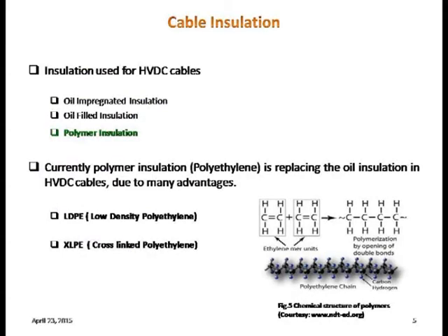So if the two power systems are connected through cable transmission, which is DC, then there will be more scope for improvement in the stability of a system. That is why power cables, and in the power cables, HVDC, is gaining importance. But what are the problems?